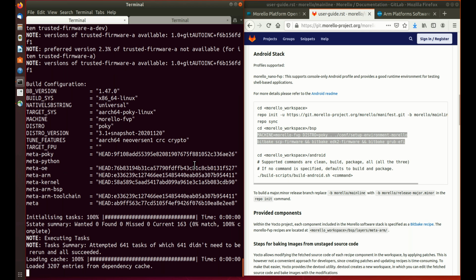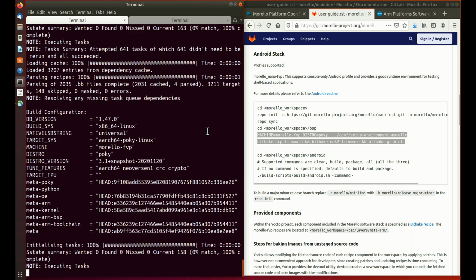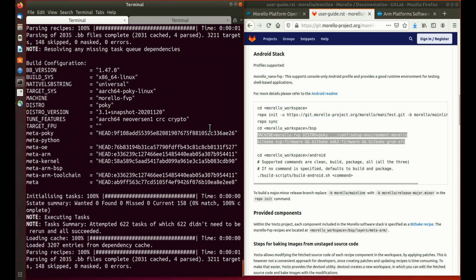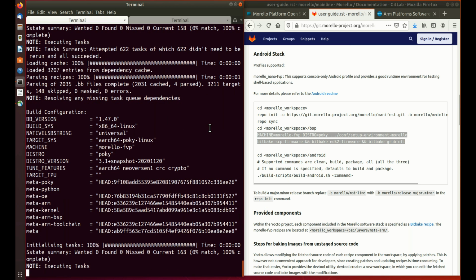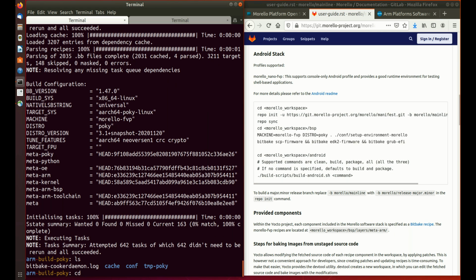The MCP and SCP firmwares are needed to initialize the platform and prepare the application processor to initially run GRUB and then the Android software stack. On completion, go to the Android folder, which is 2 levels up, and build the Android image as shown in the instructions.